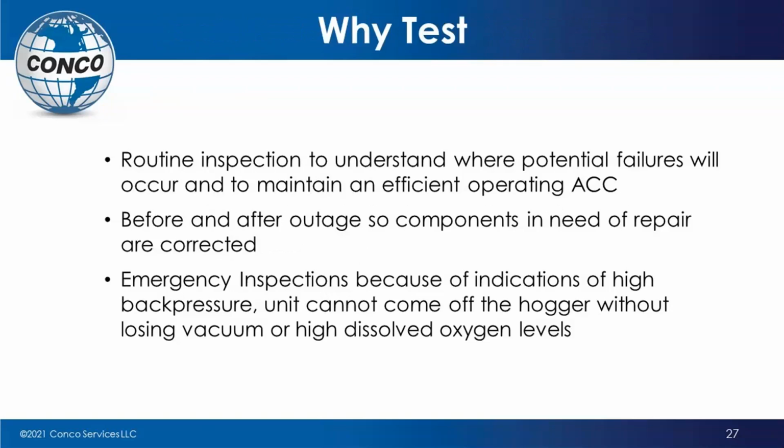Why test? Well, because if you have a leak, and every unit leaks, I don't care what type of condenser you have, I don't care what type of power plant you have, there is air in-leakage in that unit itself. The question is, when does the amount of air in-leakage overcome the unit's ability, or the air removal system in the unit, to remove all that air? And thus it becomes a real problem because now it is impacting your particular unit and, back to how many megawatts you can generate. So we say, hey, why don't you take a look at a routine inspection?